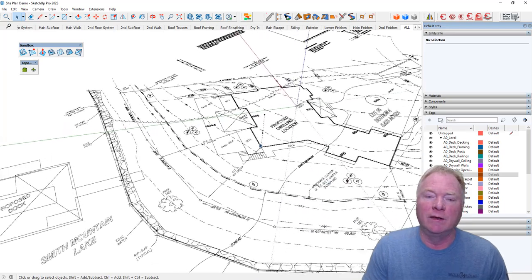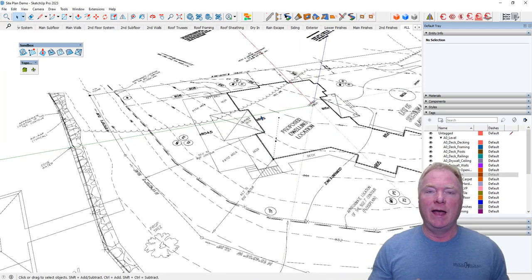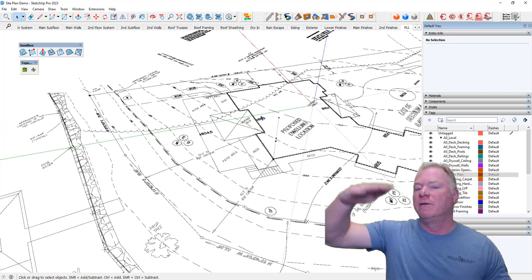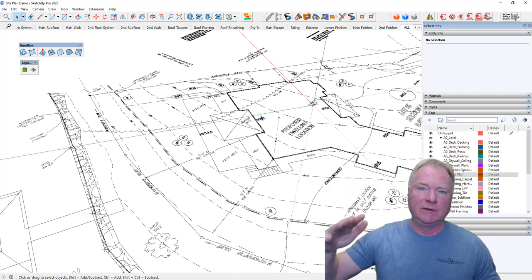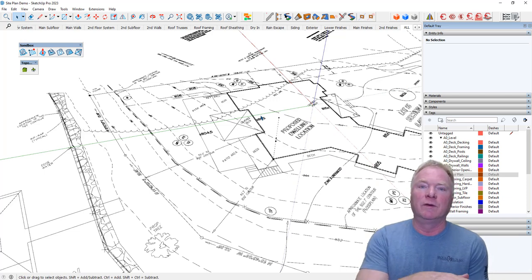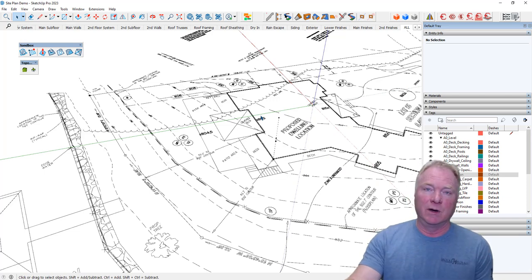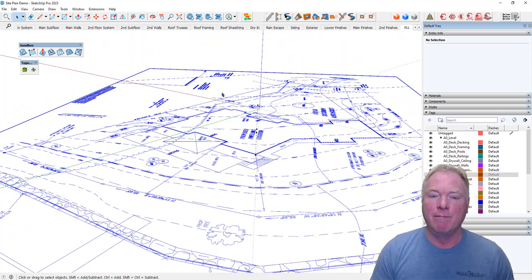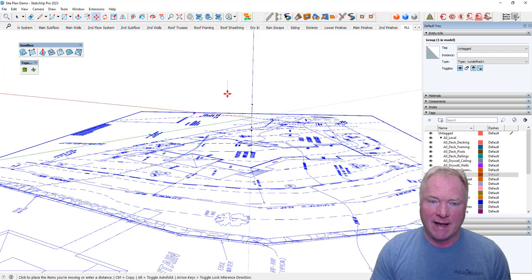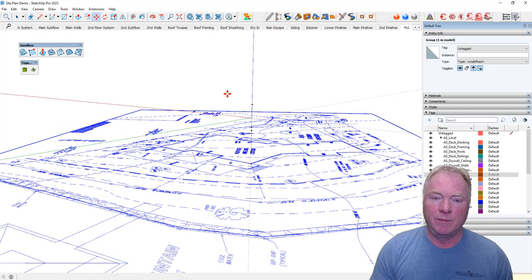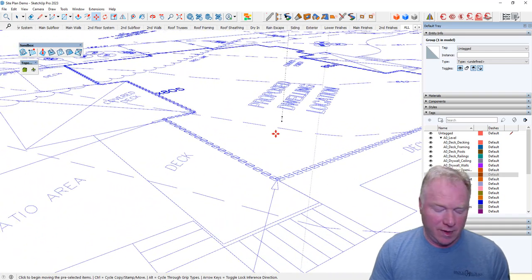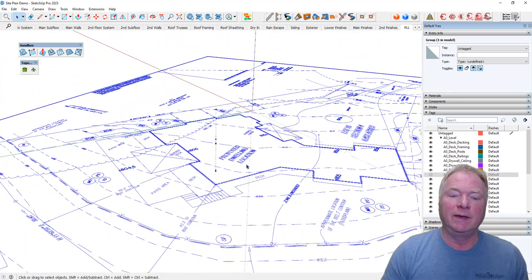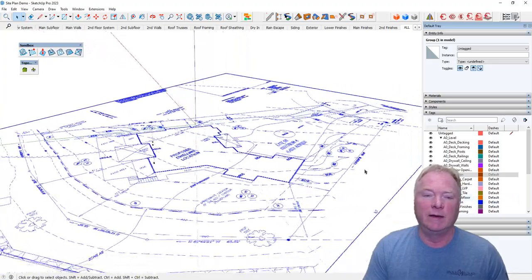So what I'm going to do now is I'm using that 805 as a reference. Now I don't want to do 800 feet above my model here. You know, that's just getting kind of silly. So I'm going to use 800 to consider that as 0 in terms of our elevations. So what I'm going to do is take this site and move it down 5 feet, because the basement slab would then be 5 feet at the 805, right? So that's what we're considering the 805 to be, at the slab. And this is down to the 800.